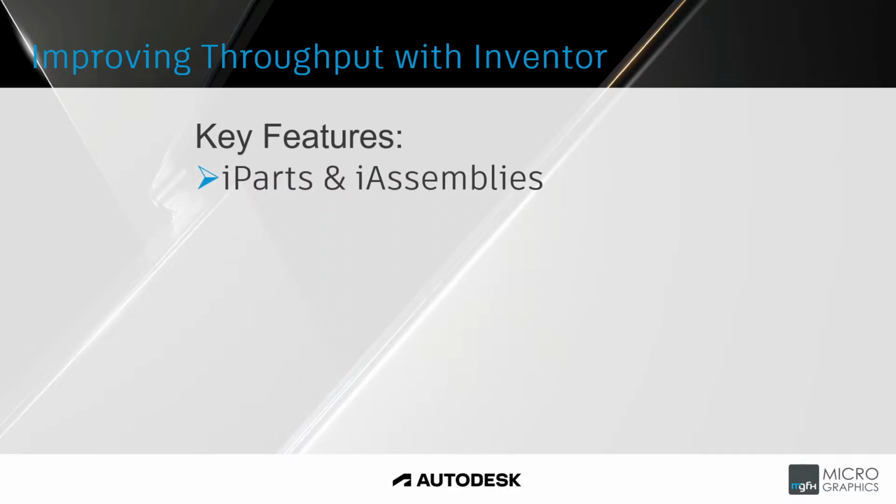Now, iParts and iAssemblies quickly generate design variations for products and families, and you can also use iParts and iAssemblies for reuse. Your design reuse tools, where you can also utilize derived components and use design assistants to repurpose existing data.